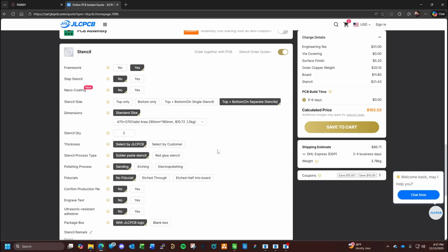So in assembly and processes like that, what you can do is, for SMT parts that are going on the bottom of the board, and you've got through-hole parts, say you want to wave solder this, because you want to wave solder the through-hole parts in one process without hand soldering. It's sometimes a lot faster.